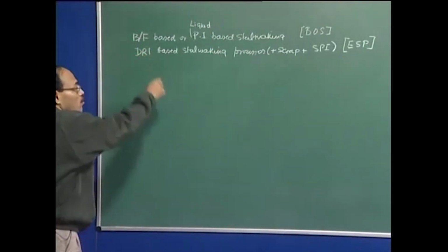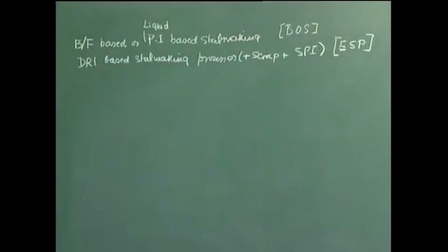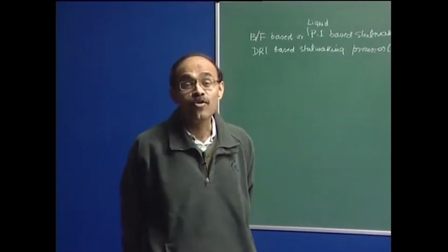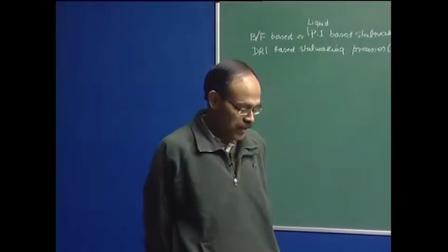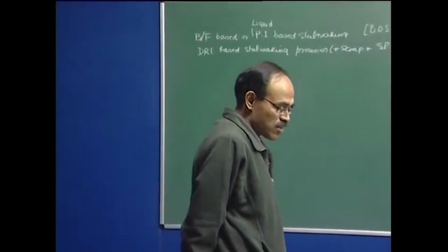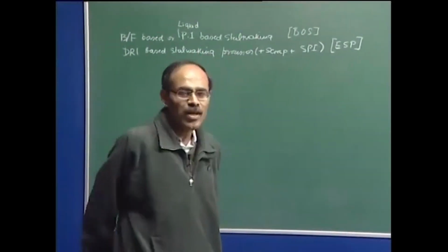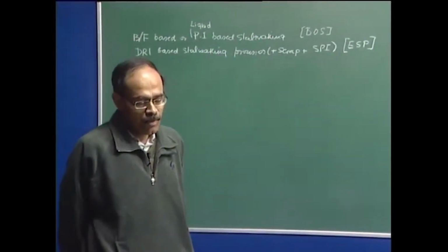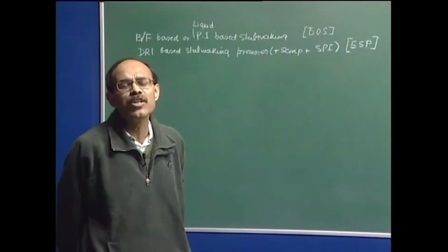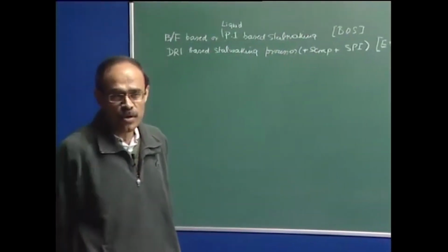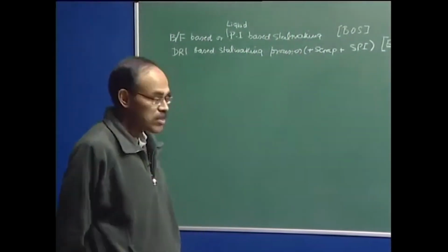Once we produce steel, which we call the crude steel, we have a series of secondary refining operations, and following the secondary refining operations today, what we have is continuous casting. As you all must be knowing, ingot casting has been phased out. Of course, in certain specific areas ingot casting is still practiced, but at a very minuscule level. More than 95% of the world steel produced today is cast through the continuous casting process.